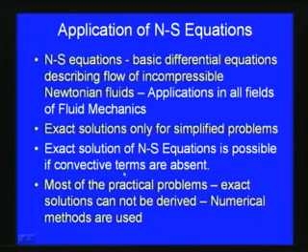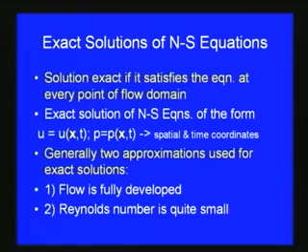solutions. So, exact solutions of the Navier-Stokes equation are only possible if convective terms are absent. As I mentioned, for most practical problems we cannot derive exact solutions, but for simplified boundaries and simple cases wherever the convective terms are absent, we can derive some of the exact solutions. So, here we will discuss a few of the exact solutions before we discuss briefly the numerical solutions for the Navier-Stokes equations.